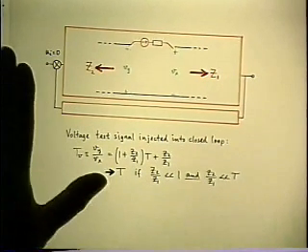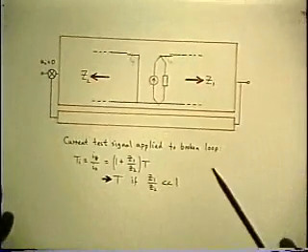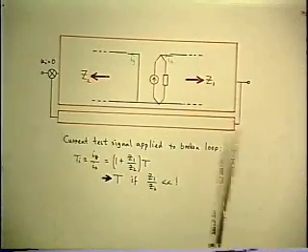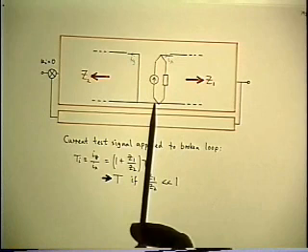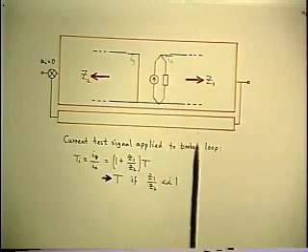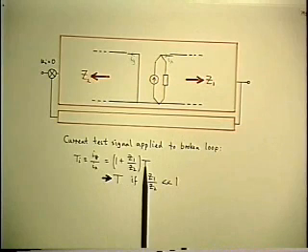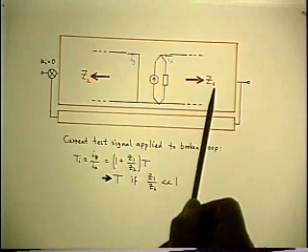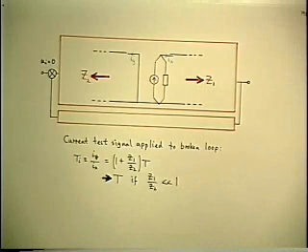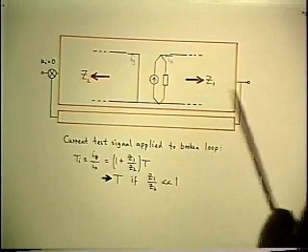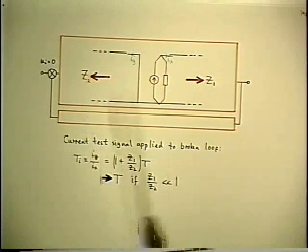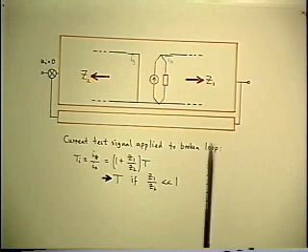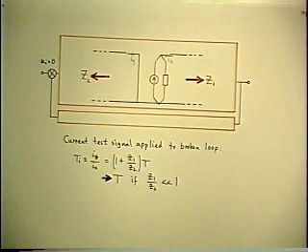That's half of it, and then you have the same things to say with respect to current injection. Same generalized amplifier, but if you're considering doing current injection now, you still have two choices. If you break the loop and apply an independent current, you get the wrong answer, but it will be close enough to the right answer if Z1 over Z2 is much less than 1, which is the reverse inequality from what it was for voltage injection. That confirms what we knew already. They are mutually exclusive. Only one can possibly give you the right answer, but maybe they're both wrong. They certainly won't be both right.